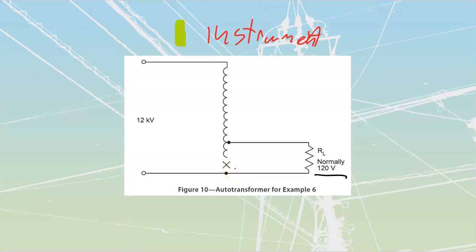We're going to take a look later on at a capacitive voltage divider, and then we can sort everything out from that, but they will never use autotransformers to step down these ridiculously high values of voltage. Usually, when we are dealing with an autotransformer, it is never going to be much more than a 3-to-1 ratio, high side to low side.